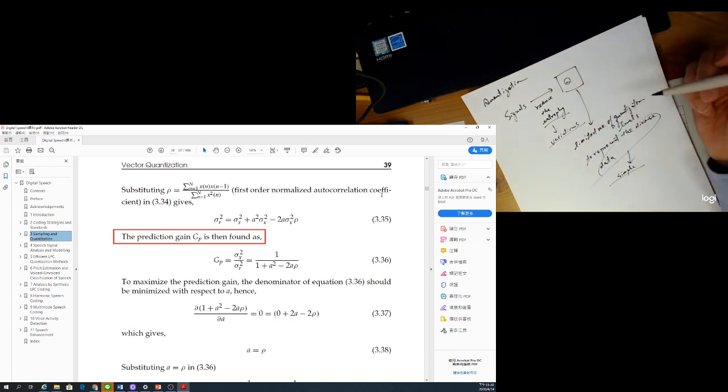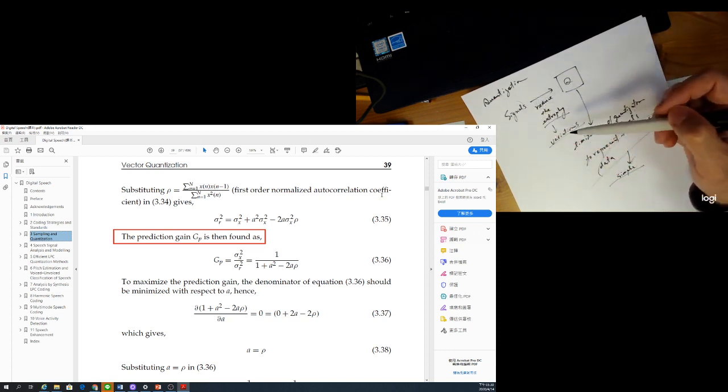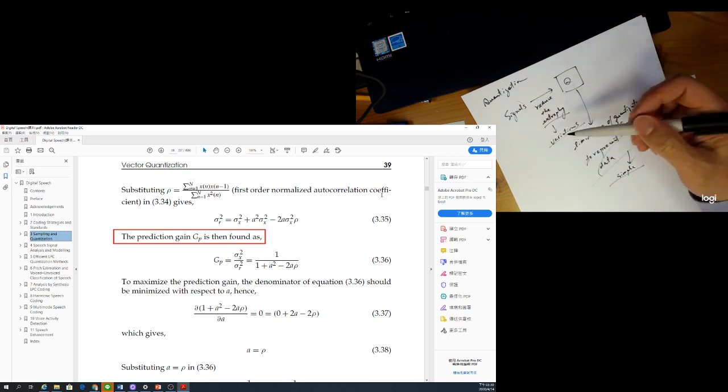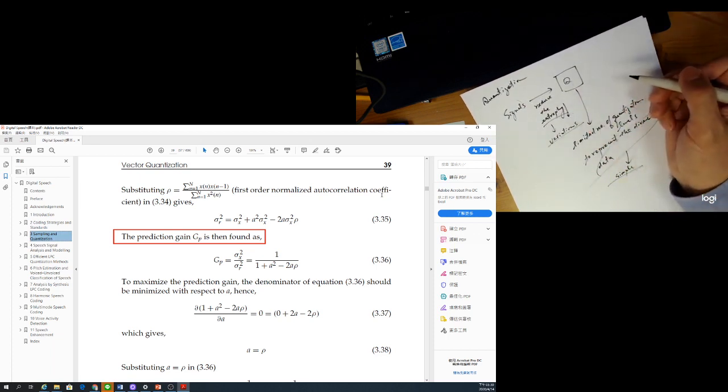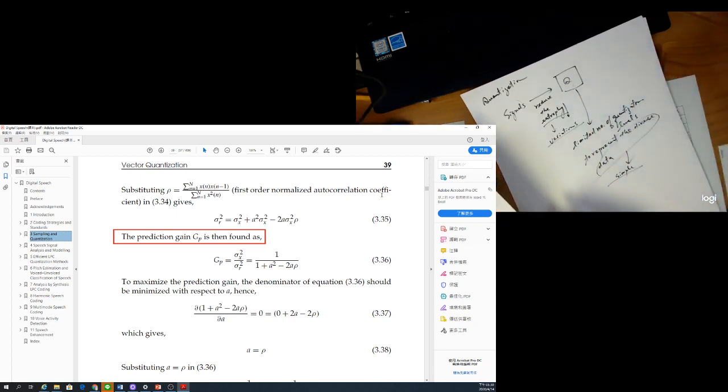The main idea is to make your signal entropy lower. Previously, the adaptive quantizer divided by the dynamic range or standard deviation to make the variation smaller, so we could design a unity gain quantizer. It looks like we are trying to make your signal uniform, so the data is easy to quantize.